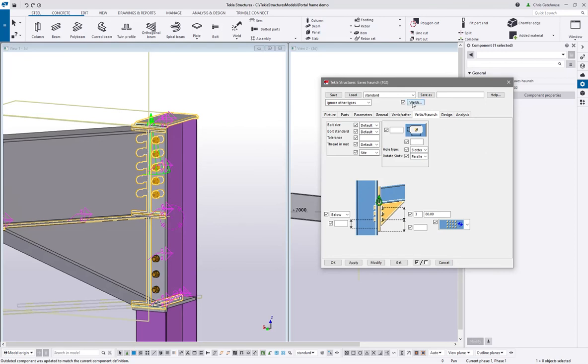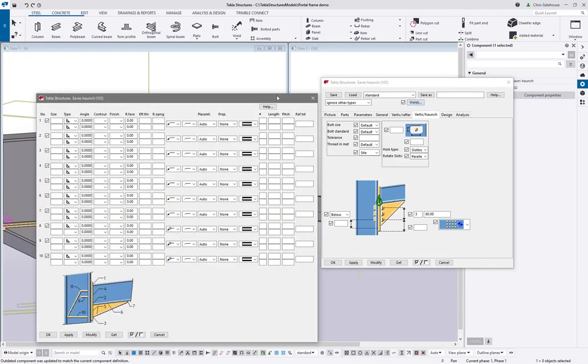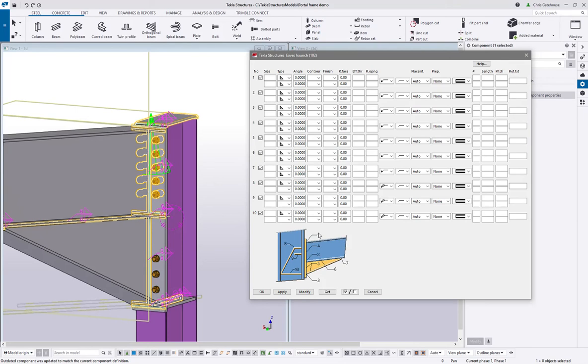And then finally the welds. And again, similar to the base plate, you will see that we've got a diagram with all the welds numbered with corresponding lines for each weld. And we can just start to sort of populate this. So let's put an 8 on the top flange with the plate, and in the web we'll also have an 8. For the bottom flange, we'll reduce that, we'll put a 6. Weld number 3, which is the bottom of the haunch, again we'll put an 8 on that one.